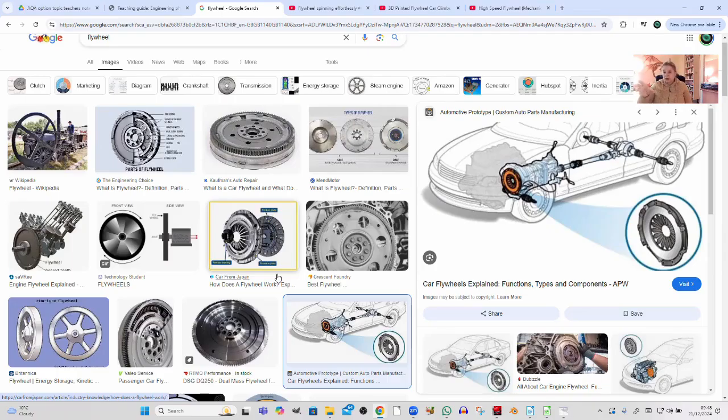And that is a 4-stroke engine, but you can see there's one power stroke for 4 movements of the piston. And so the power delivery from a 4-stroke engine is really lumpy, and flywheels can smooth that delivery. So you store energy in a flywheel.